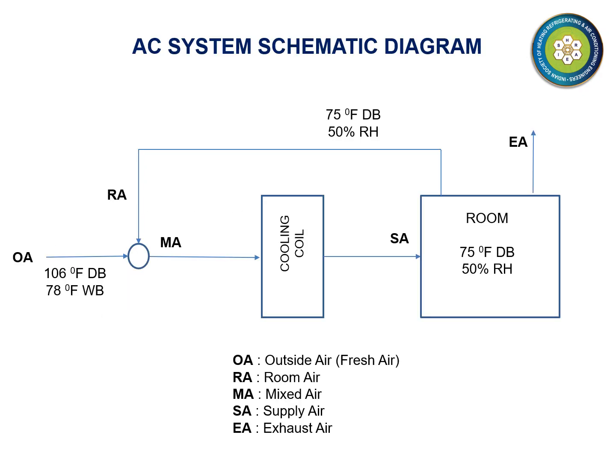The AC system's schematic diagram is shown on this slide. As you can see, outside air, denoted OA, is introduced into the air handling unit return to become a part of the return air load of the cooling coil, unlike infiltration load, which is part of the room load. The cooling coil, besides cooling this mixed air, denoted MA, may also have to dehumidify it so that the room humidity specs are met.